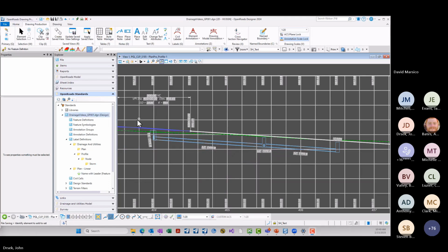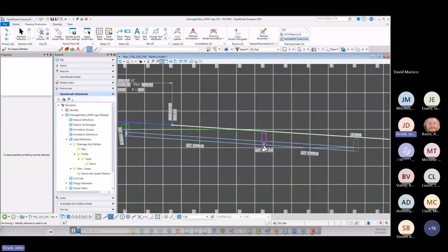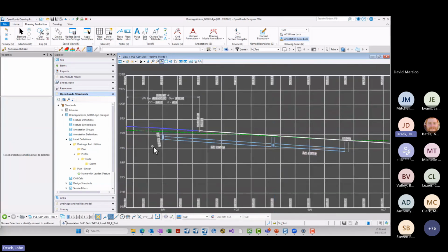So when it comes to the crossing pipes, or these pipes that are coming out, that's what gets auto annotated, since it's a conduit and so it placed it there. Maybe you switch that to have a leader line, switch to a labeler. So I'm deleting those out. You could have used remove element annotation as another way to remove that.